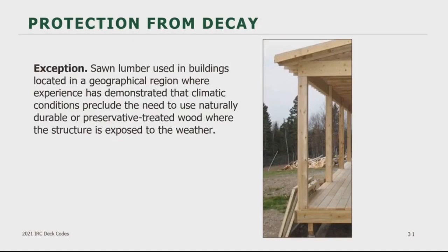There is a geographical exception to this section in the code. If you live in an area where decay is not a problem due to the climatic conditions of your region, the building official can exempt the requirements for preservative treated or naturally durable wood.